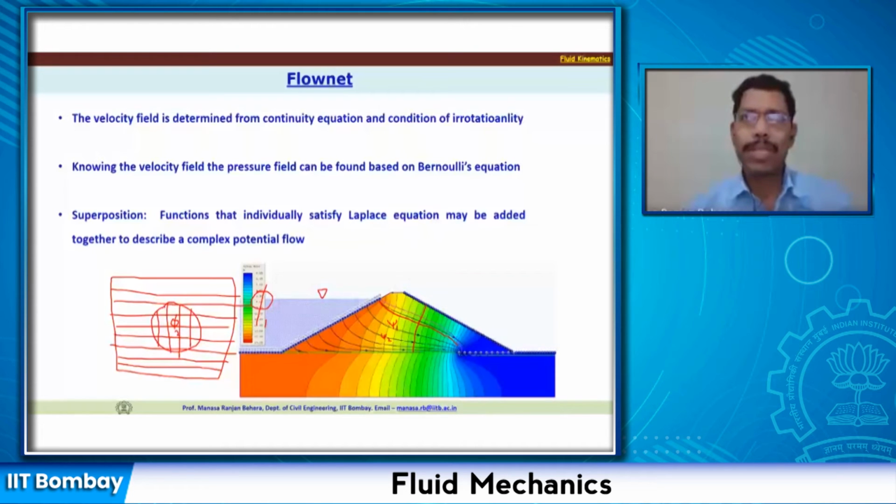So whatever discharge is coming through this is going to also pass through this. And we have also seen another property, there cannot be any cross flow across the streamlines. So the discharge that is coming through this is passing here. So if the discharge is the same, we know that this is a larger area or width and this is lesser width. So the same discharge passing through a lesser width will result in higher velocity.